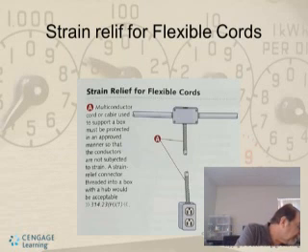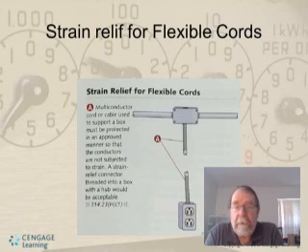It's basically a multi-conductor cord or cable used to support a box. It must be protected in an approved manner so that the conductors are not subject to a strain. Usually they have a wire mesh around them. The conductor goes through the middle of the wire mesh, and the wire mesh handles it. Now we have conductors that provide 220 to some of our equipment in our labs, and they use the cable that's specially made for that.